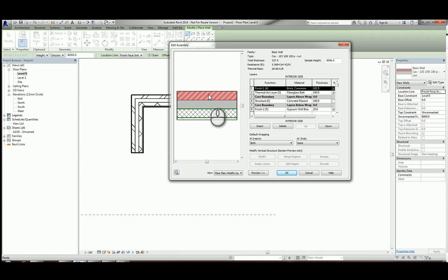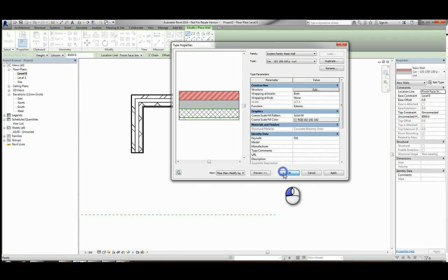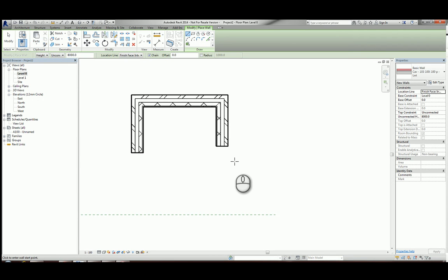Okay, and it's the same on the inside. The plasterboard is just a finish, whether we've got plasterboard on dabs, on battens, or a wet plaster finish inside there. It is just purely a finish inside there to make it look nice, and obviously to give it some thermal rating as well. So that's how the core boundary and the core faces are located within my wall. So when I'm drawing in, I'm going to ask you this question: which one should I use?